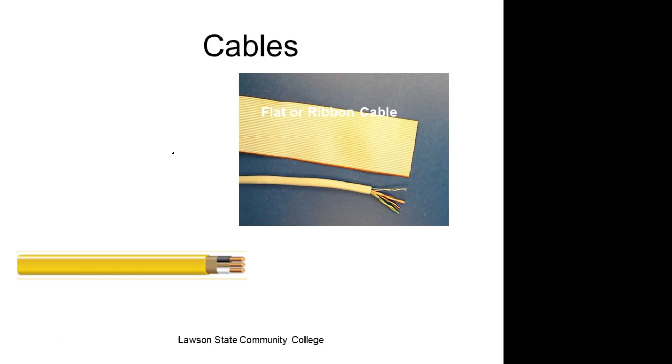And you should have a ground fault on anything that's close to a source of water. So if you got any outside plugs, it should be on a GFCI. If you got a plug in the bathroom, it should be on a GFCI, next to the sink. If you got one in the kitchen, you should have a GFCI. Within, I think it's 8 feet. If you got a plug within 8 feet of a water source, it's supposed to have a GFCI. It's got to reset back on. It's got to push the test too. Yeah, the red and then the black. It's got to push the test.